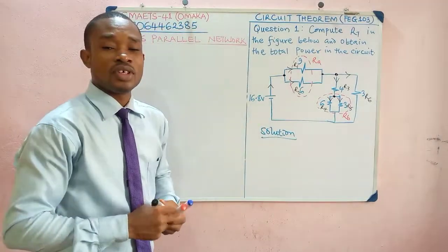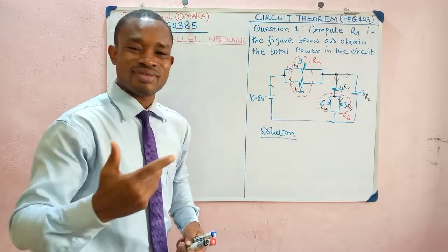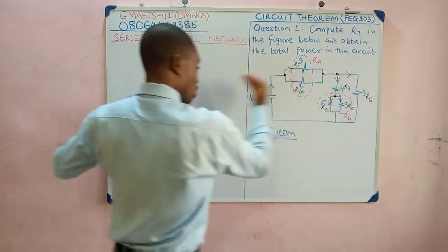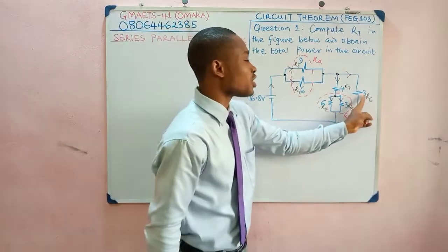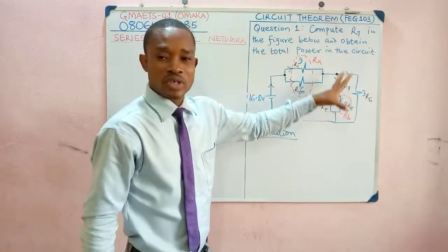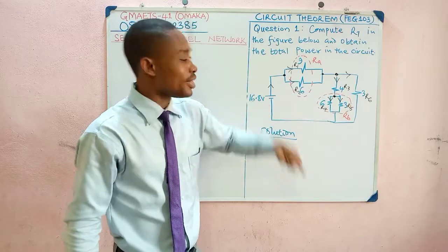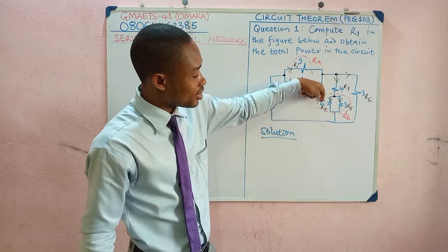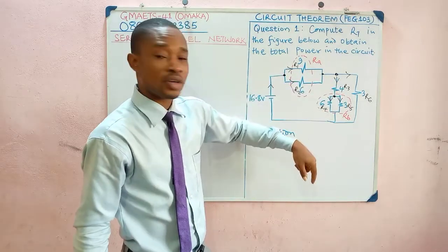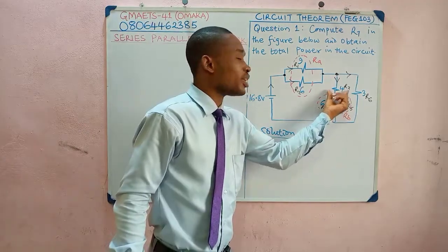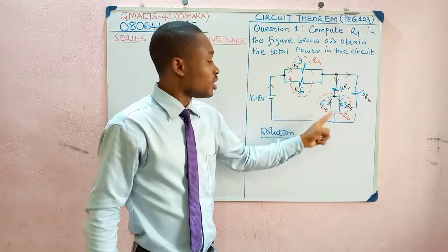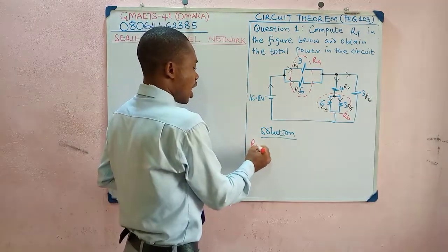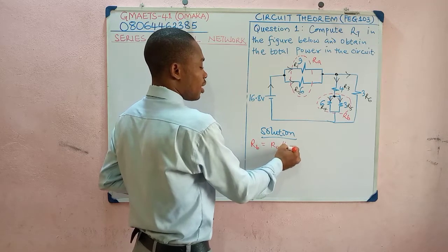We can now solve. Remember, for series parallel network, you resolve towards the what? Source. So we'll start our resolution from here, coming this way. However, we won't solve this 3 ohm resistor together with this 4 ohm resistor in parallel for now yet. Why? You notice that the current entering this 4 ohm resistor, the same current shares and enters the 6 and 3 ohm resistor here. Therefore, we need to resolve everything that is happening here internally first. Is that okay? These two are in parallel. So let us obtain RB then. RB is going to give us R4 parallel R5.